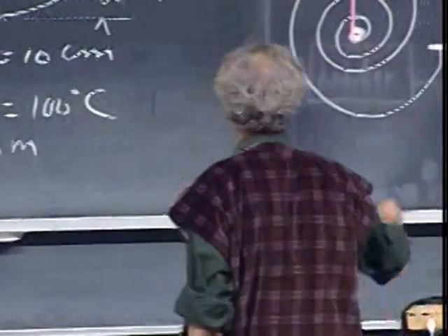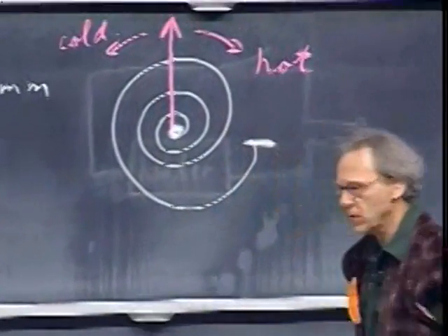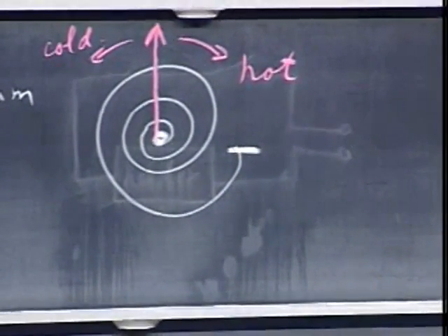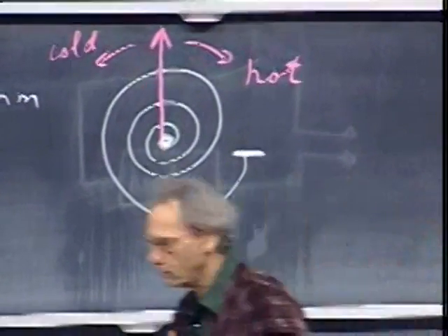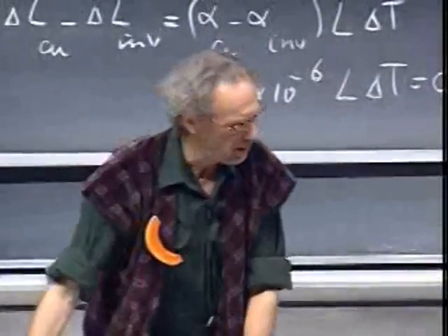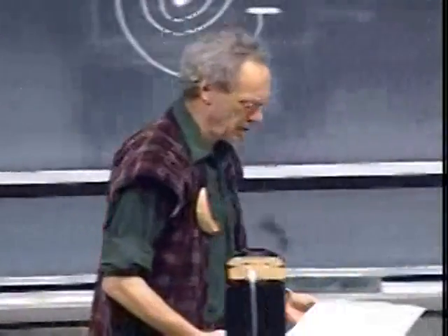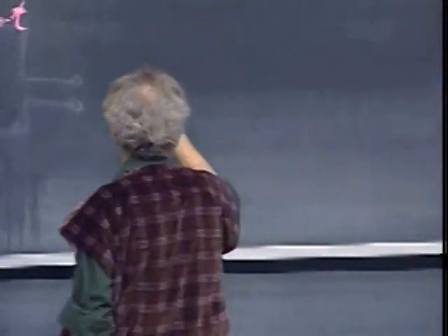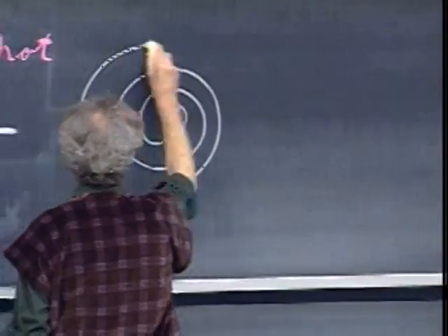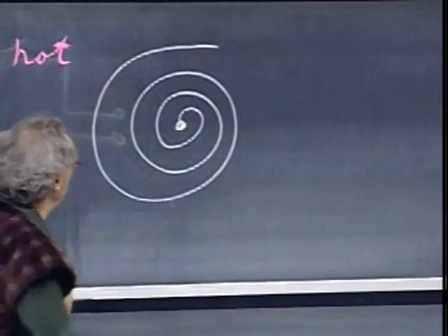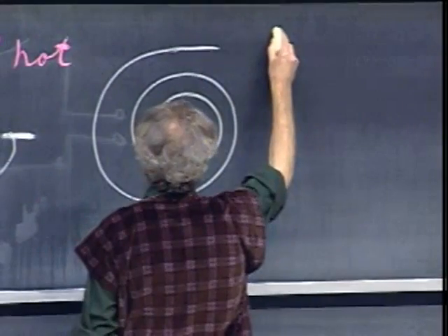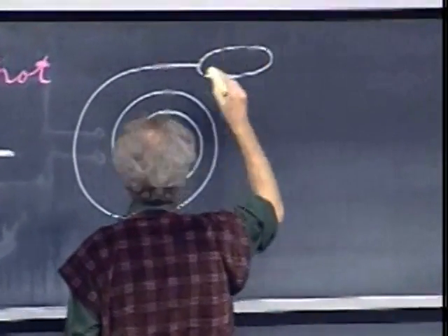Your thermostats in your dormitories, of your heating systems and also perhaps of the air conditioning systems, almost all have a coil like this in there. It's an extremely ingenious device. It has a coil, and at the end of the coil is a little glass tube. It's only 1 centimeter large, and there is mercury inside. So the coil is like this. Bimetal. And at the end here is a glass container, and there is some mercury.